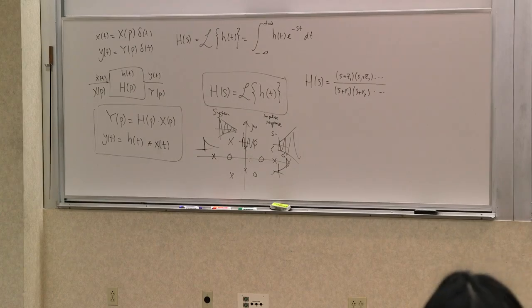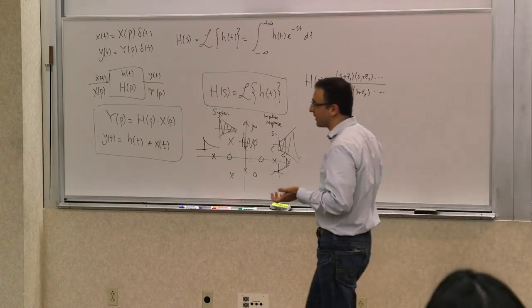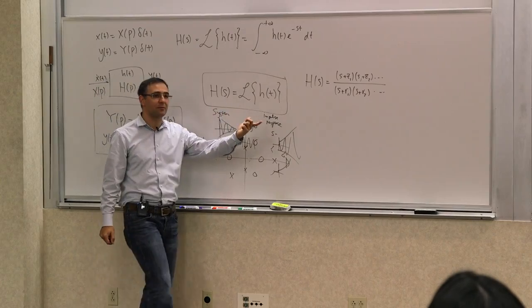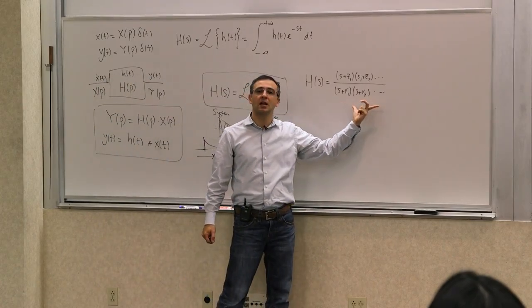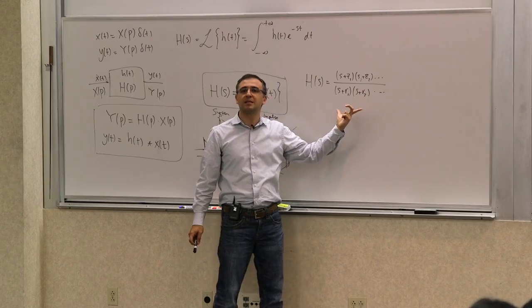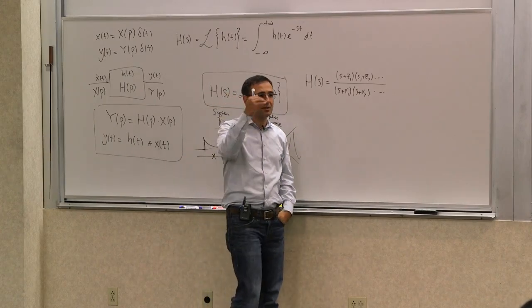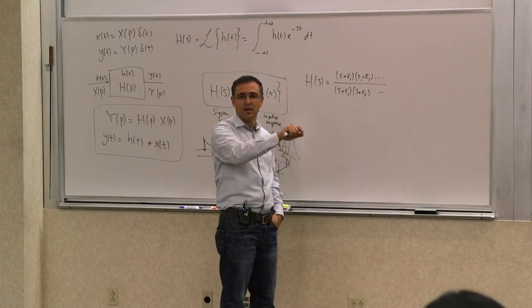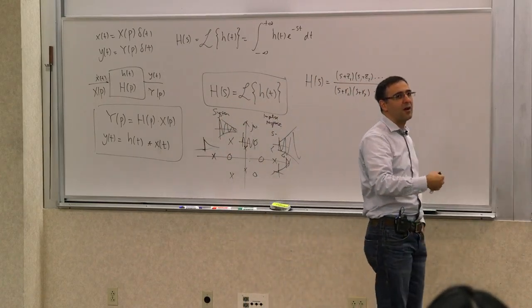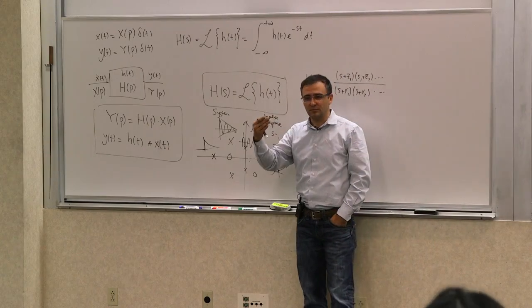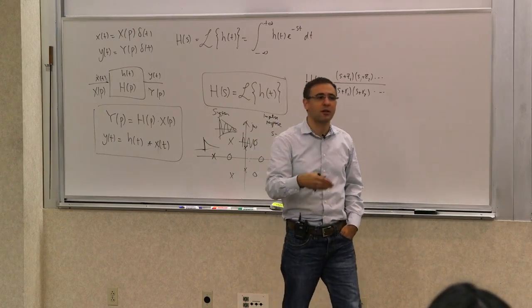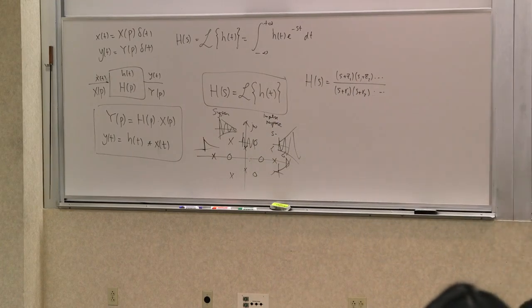Now, we also saw that there are many criteria for determining stability. We haven't talked about all of them. The simplest one for determining if the system is stable or not, if you're given a polynomial, was the Routh-Hurwitz method, which was basically you took every other coefficient and wrote them in two rows, and then did cross multiplication and division by the term that was closest to you. You wrote them down, and for every change of sign in the first column, you had one right half plane pole. It doesn't tell you anything about the zeros, really.